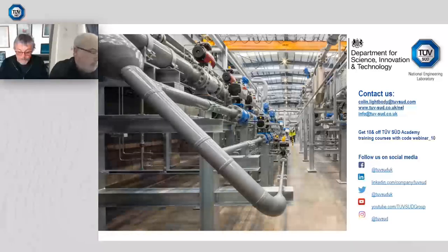If you're right, John, if we assume it's a highly variable flow rate, as in a large turn down ratio, the meters I would go for, and this might be the answer to quite a few questions actually, are a liquid ultrasonic meter or a Coriolis meter. And the differentiator there for me, so they both have very high turn down ratios, if they're calibrated well. If you're measuring the mass of the oil, you might want to go for a Coriolis if you can get it sized properly. If you're measuring the volume, then either the Coriolis or the ultrasonic.